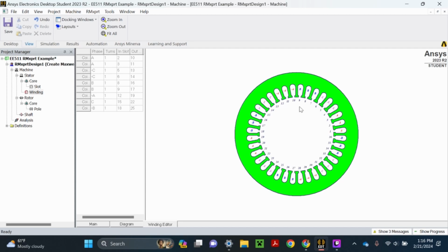And because I have more than 2 slots, I have 9, I can do sinusoidal coil distribution. So this has the luxury that I can put sinusoidal. So my flux doesn't look like a wall, it looks like a sine. So the torque would be smoother. Okay, just wanted to add.